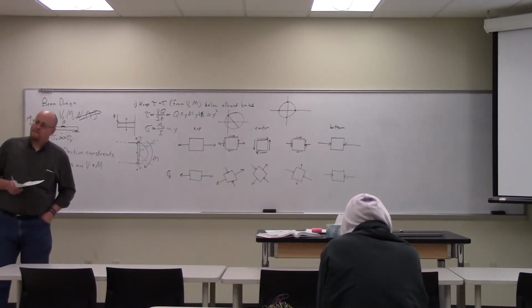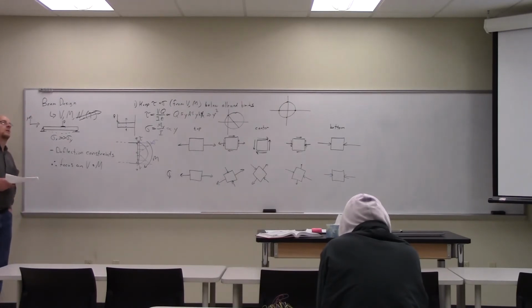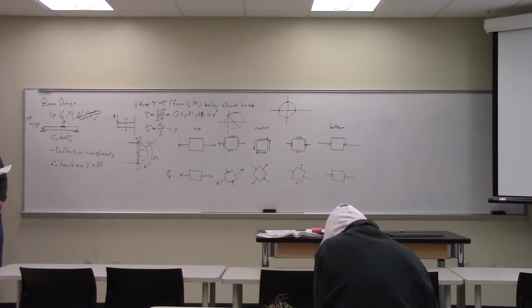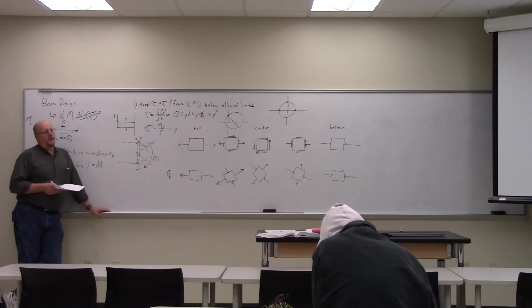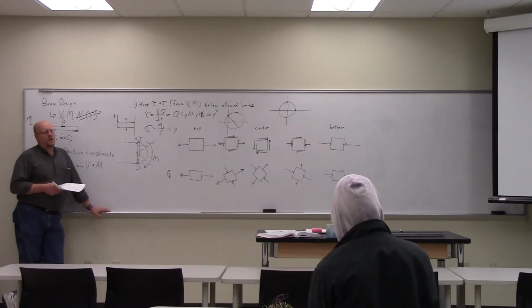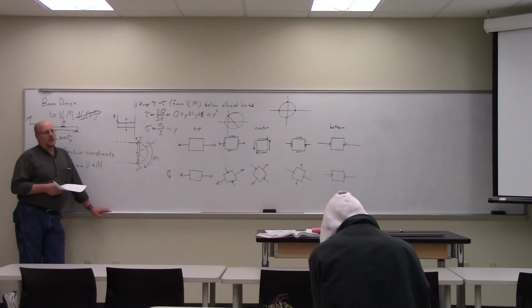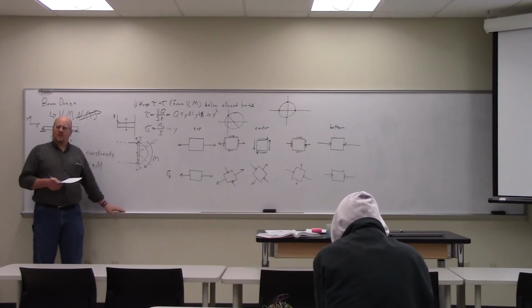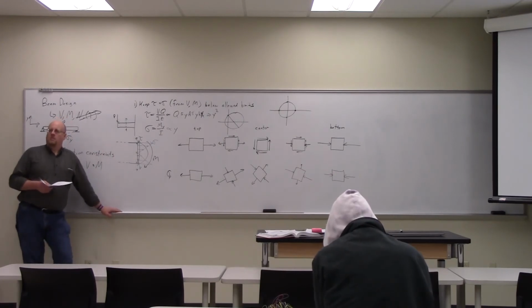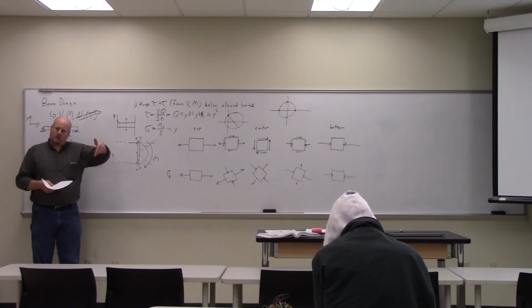Could it be discontinuous? You just made it sound like it might be. Well, it's hard, because in an I-beam you change orientations when you go from the flange to the web. Right. So the shear flow takes a right angle turn. Right, I remember seeing that in the book. So it is discontinuous. It's not really discontinuous. But the orientation changes as your perspective changes; in other words, here this is sigma xy, here it's sigma xz or whatever.